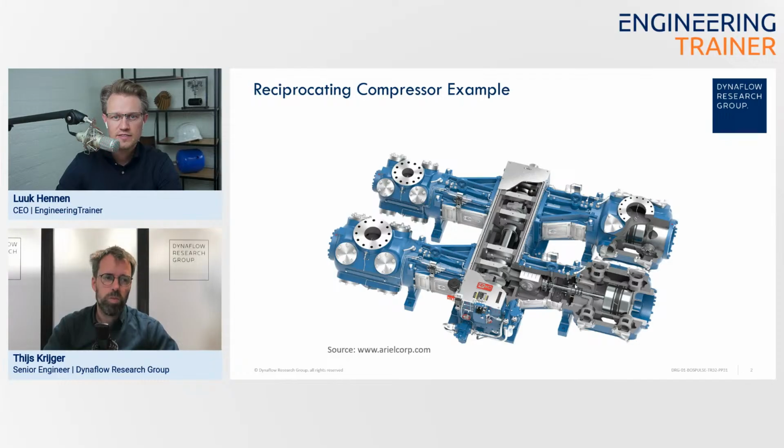Yeah. So for example, when we're looking at this compressor system, there's API 618. It's the governing code for these types of reciprocating compressors. And there's a table at the start of the pulsation section which gives these limits.